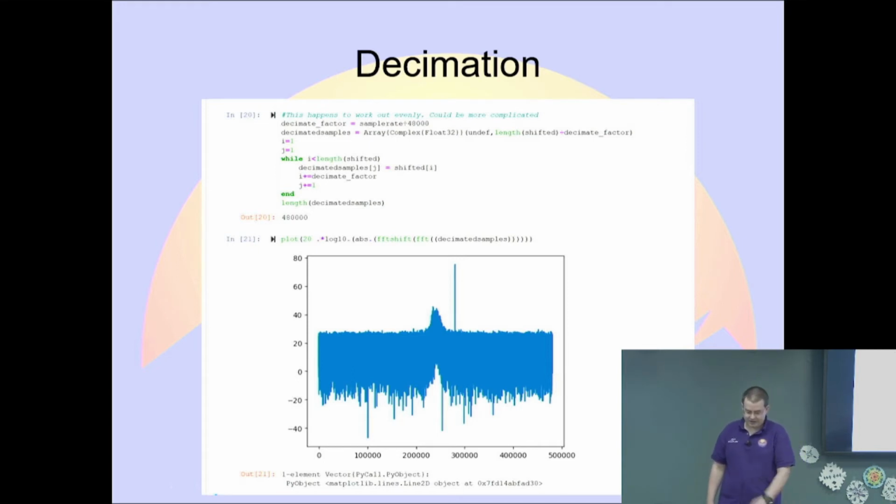If we plot the spectrum again in the frequency domain, we notice that we have our original signal still here, which is good. And we have some artifacting, which is less good, because we're kind of capturing the high frequency components. And lots of noise still. You will notice that we have 20 dB of just background noise. If you were doing a real receiver and not a demo talk, you might want to remove DC offsets and clean that up a little. But it doesn't matter because I didn't assume I'd have audio out, so I'm not going to do a demo.